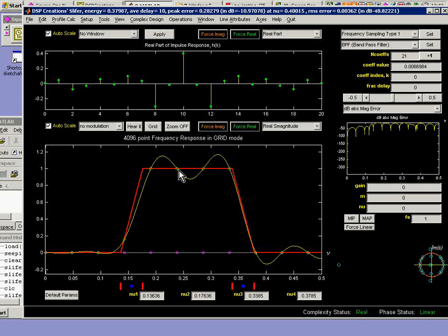And you notice these little round circles, these we call pearls. These are located in terms of frequency at equispaced points in the traditional frequency sampling manner. Very powerful design technique which has been around from the earliest days of DSP. Now these little tiny squares show the frequency locations corresponding to those pearls, and at the moment, since we have 21 coefficients, I look up in the right hand corner, this spacing is 1 over 21, because that at the moment is normalized frequency seen going all the way around the unit circle, and therefore having 21 of these little pearls that can be moved.